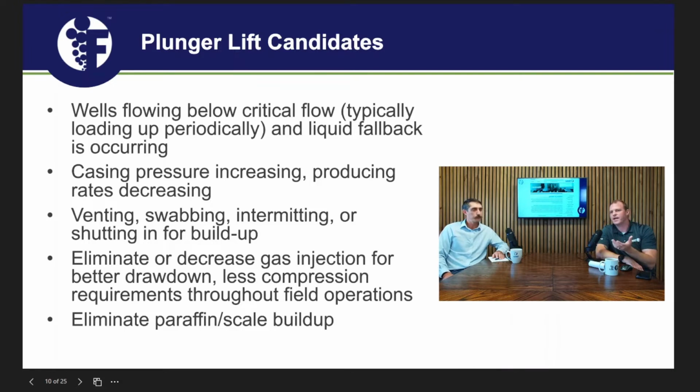In my head, I like to view this almost like an insert pump on a sucker rod pump: you can pump its cycles per minute more, but you might not get more production. Instead, you're just going to wear out the barrel or the rods or the tubing. Plunger lift's similar: you could get too many cycles for the production you're getting, and at that point, you're just simply wearing the plunger.